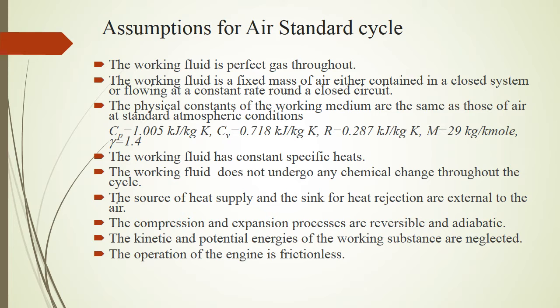Heat is supplied and rejected in a reversible manner, and if necessary can be supplied and rejected instantaneously. So this is an assumption. The source of supply and the sink of heat rejection are external to the air, but in the actual engine energy is supplied by combustion of fuel and rejected by the exhaust of gases.